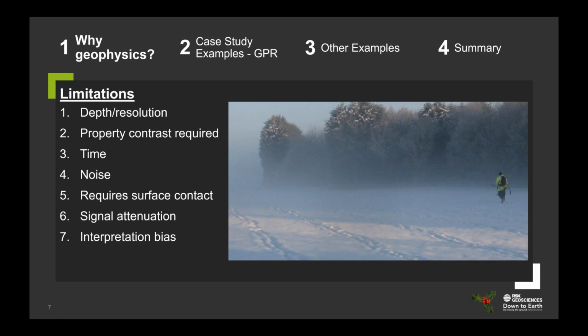There are certain ground materials that can reduce the penetration depth of the signal, or there are structural elements that can also reduce that through scattering of energy, such as rubble-filled cores or high conductivity clays. So having as much information about how a structure is constructed or what is going on in the ground will help us with designing our survey and then get the most out of it.